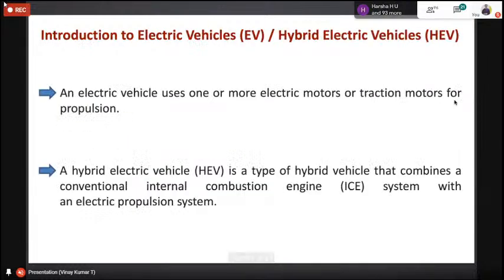The main goal or advantage of the electric vehicle compared to IC based engines is reducing the CO2 emission. Next, operation is also very smooth, right? One more advantage of the electrical drive is we can operate the drive in 4 coordinate operation: forward motoring mode, forward braking or generating, reverse motoring, reverse generating. This is the main feature.